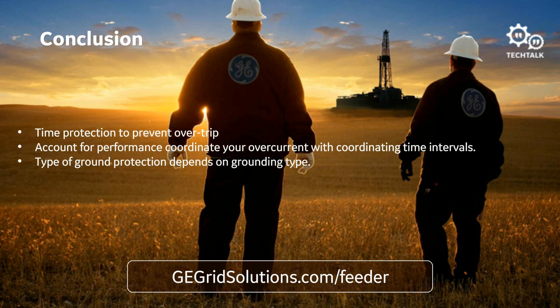So, does the TCI, the coordinating time interval, account for breaker operate time at 3 cycles? Yes. So typically the breaker operate time is covered inside of that safety margin.